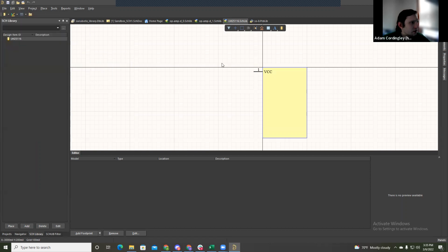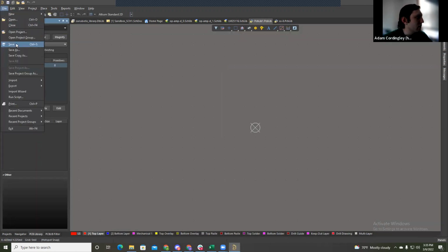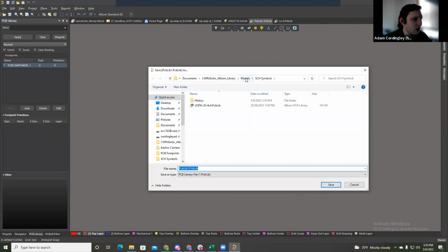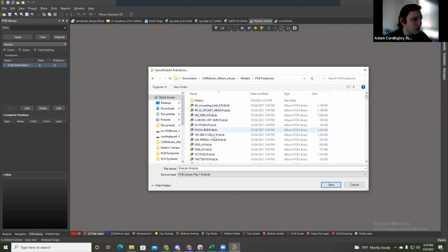So the first thing you'll do is create a PCB library. You go in here and call it something reasonably descriptive. It's a TSOP, and there's 20 pins on it. You mix up underscores and dashes and whatever, it's got an exposed pad.